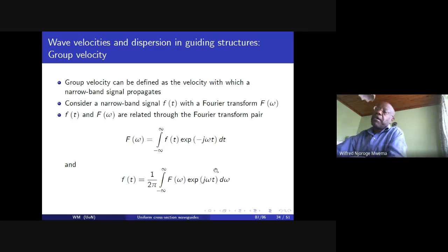The mathematical and physics way usually uses a square root of 2 pi everywhere, for both the forward transform and the inverse transform, to try and get symmetry. But electrical engineering will use this more unbalanced form, where the Fourier transform itself is not divided by twice pi, but we put the twice pi in the inverse Fourier transform.